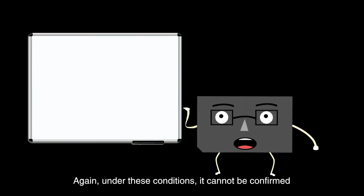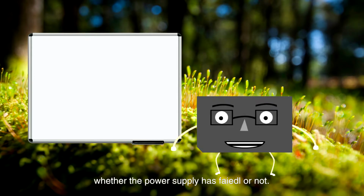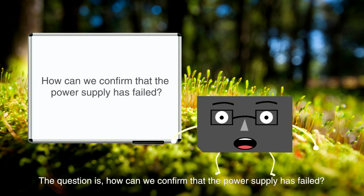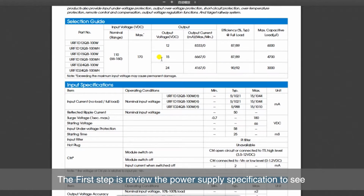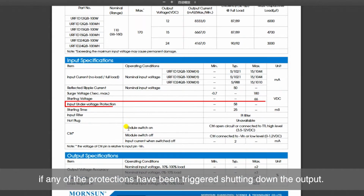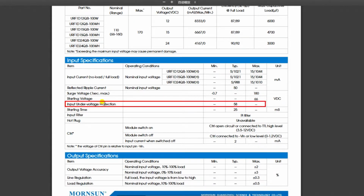Again, under these conditions, it cannot be confirmed whether the power supply has failed or not. The question is, how can we confirm that the power supply has failed? The first step is to review the power supply specification to see if any of the protections have been triggered, shutting down the output.